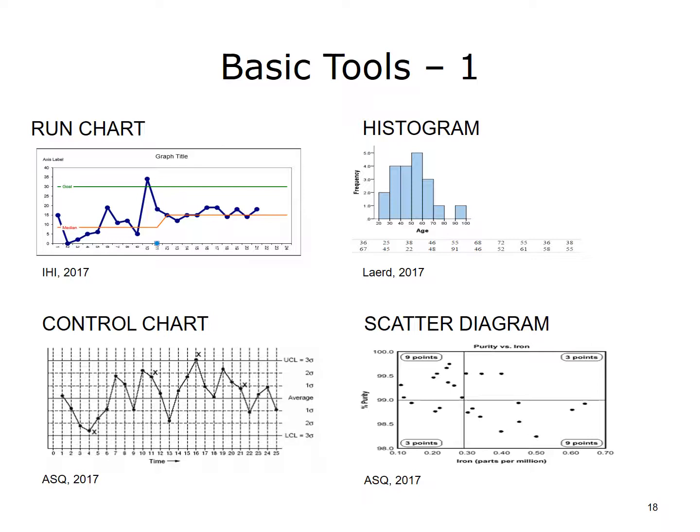A control chart is used to monitor and analyze variation from a process to determine if that process is stable and predictable, comes from common cause variation, or unstable and not predictable, shows signals of special cause variation. Histogram. A histogram is a graphical display of the frequency distribution of the quality characteristic of interest. A histogram makes variation in a group of data readily apparent and assists in an analysis of how data are distributed around an average or median value.